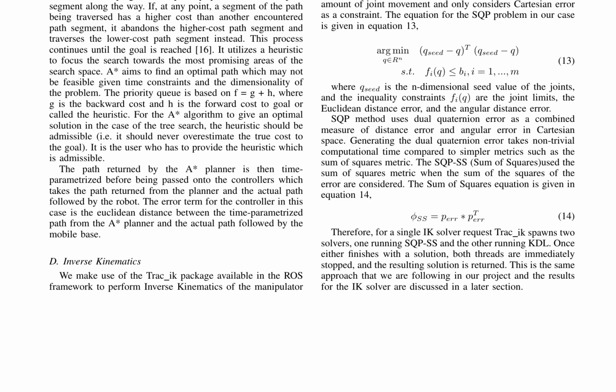Upon movement of the robot's base, inverse kinematics is performed using the TRAC-IK solver within the ROS framework. This solver outperforms classical solvers, such as Orocos's KDL, with an average solution time of 0.44 milliseconds and a higher success rate. Trajectory planning is subsequently carried out for both the manipulator and mobile base of the Fetch robot.